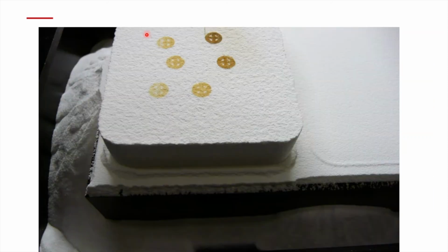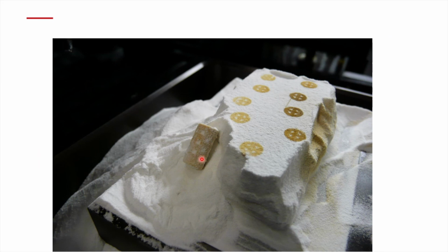Here you see the powder bed pushed out of the printer. Here are the printed parts. They're brownish because there's a heat treatment for cross-linking the binder, which is not completely homogeneous. But you already see that the packing density is high because you see that this is not flowing. It's a flowable powder, and generally it flows. But due to the high packing, it's coming out as a block. And then you can see that we scatter now the parts into the powder bed. There's no support structure anymore, and the parts look nice.